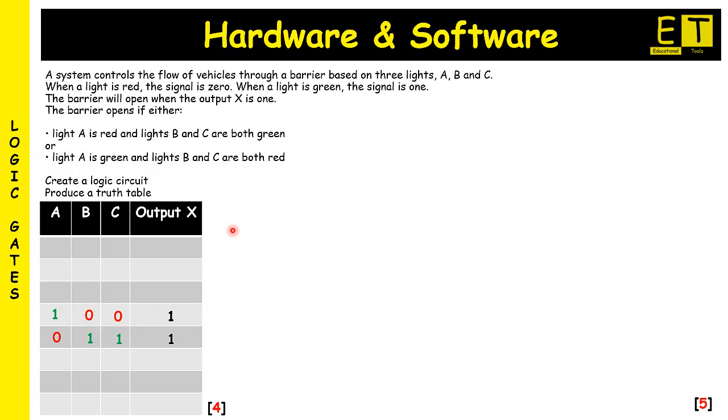So to do this, we actually know now X is equal to 1 when A and not B and not C are input into the logic circuit. So we can actually write this down as X equals 1 if A and not B and not C.